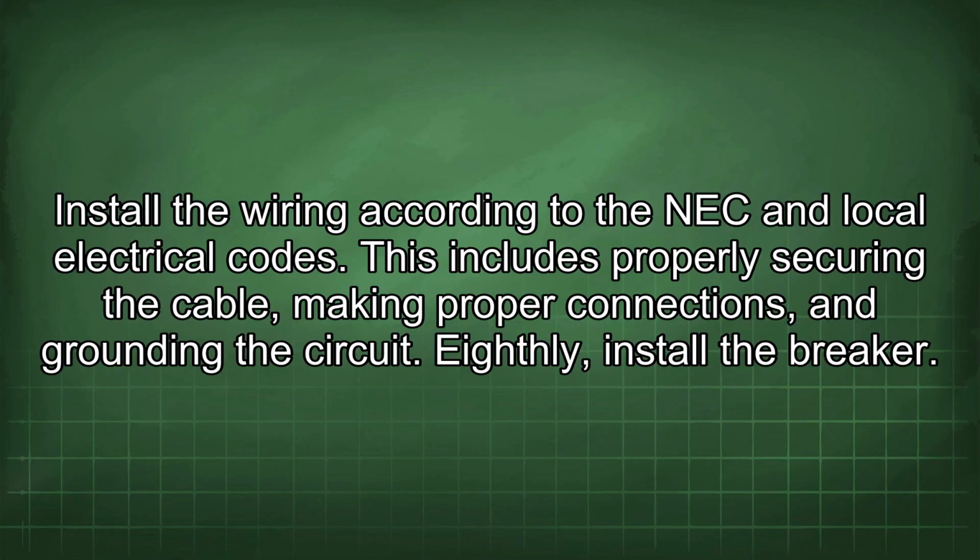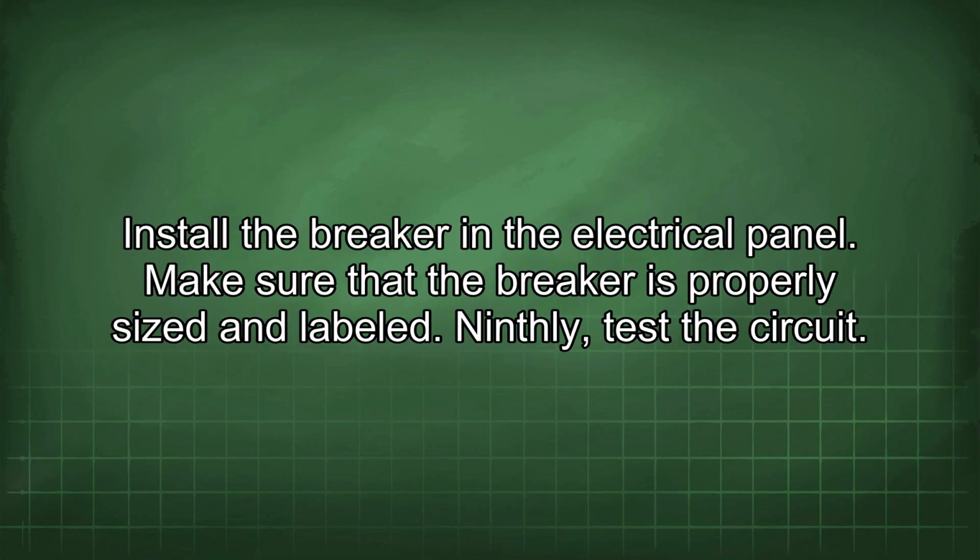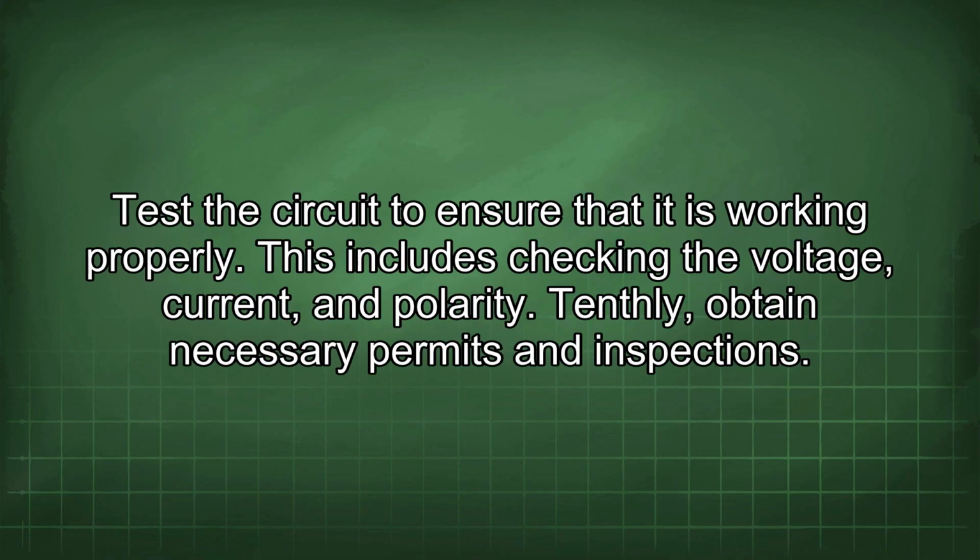Eighthly, install the breaker. Install the breaker in the electrical panel. Make sure that the breaker is properly sized and labeled. Ninthly, test the circuit. Test the circuit to ensure that it is working properly. This includes checking the voltage, current, and polarity.